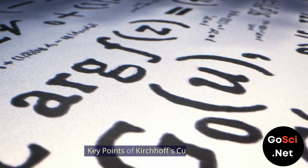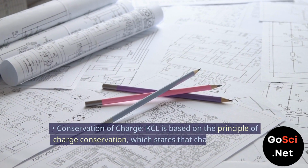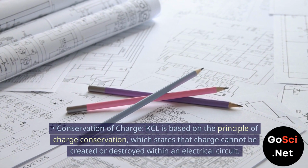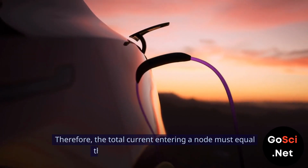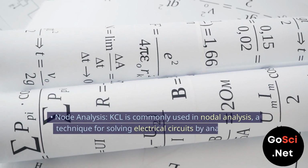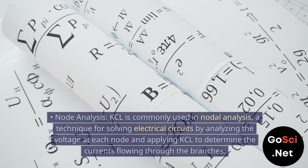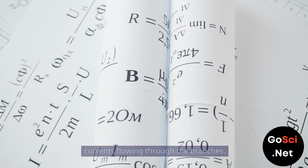Key points of Kirchhoff's current law. Conservation of charge. KCL is based on the principle of charge conservation, which states that charge cannot be created or destroyed within an electrical circuit. Therefore, the total current entering a node must equal the total current leaving the node. Node analysis. KCL is commonly used in nodal analysis, a technique for solving electrical circuits by analyzing the voltage at each node and applying KCL to determine the currents flowing through the branches.